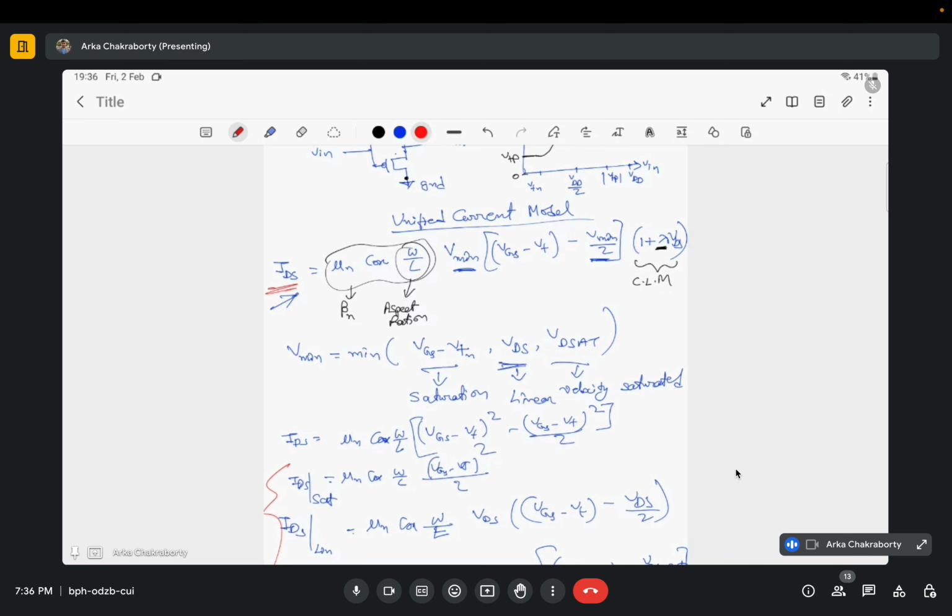So for designing circuits, we need to know about W and L. W and L are in our control, but we need to know the expression of current, and if I use certain VG, VT, what IDS I will get. If you use some simulator like HSpice or Spectre or Virtuoso, that is Cadence, or even a simple simulator like LTspice, you will be using some models, and this model contains all the rules for designing VLSI circuits.